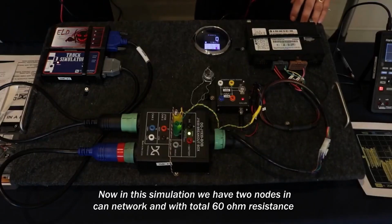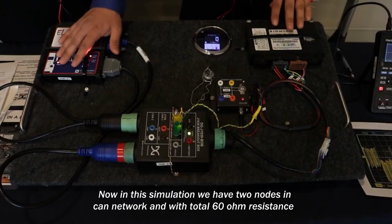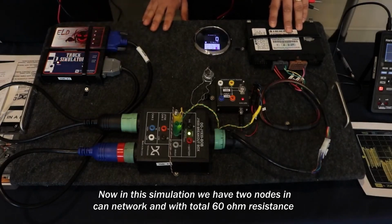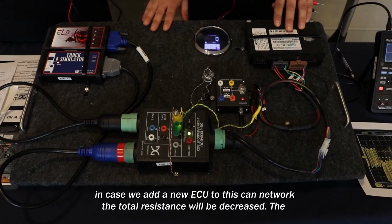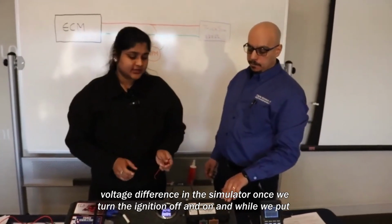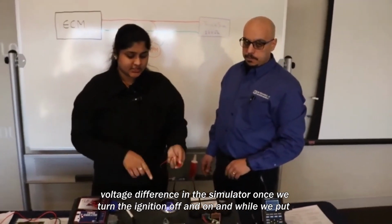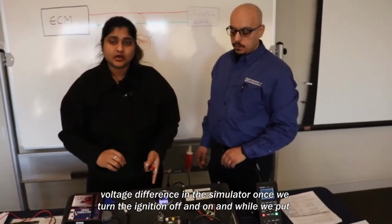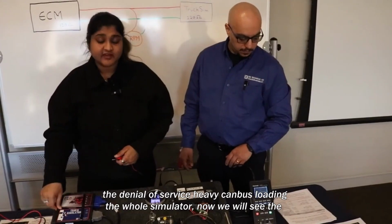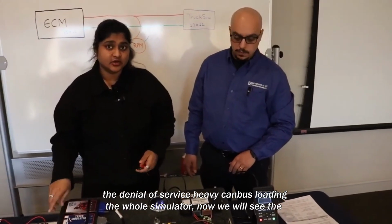Now, in this simulation, we have 2 nodes in the CAN network with a total of 60 ohm resistance. In case we add a new ECU to this CAN network, the total resistance will decrease. These are the voltage differences in the simulator once we turn the ignition off and on, and while the denial of service heavy CAN bus load is on the whole simulator.